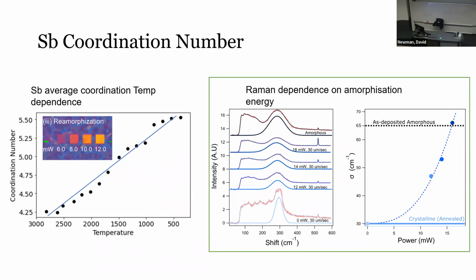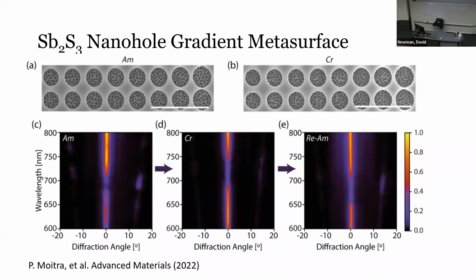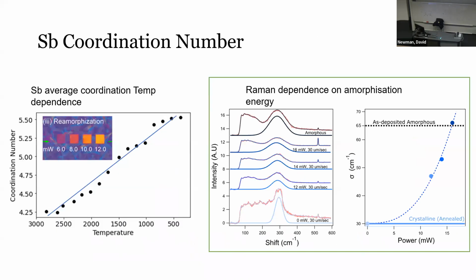Our ultimate aim is not to use different sized resonators, but the same size resonator, and to gradually amorphize to different levels of refractive index, so that we can achieve different resonances not by size or geometry, but by the optical state of the material.